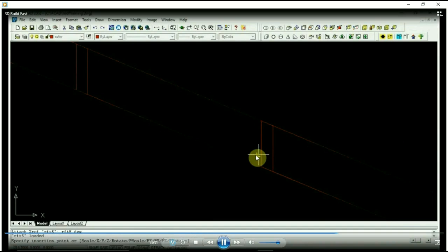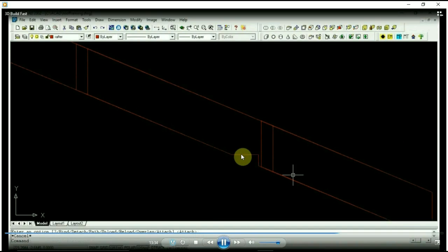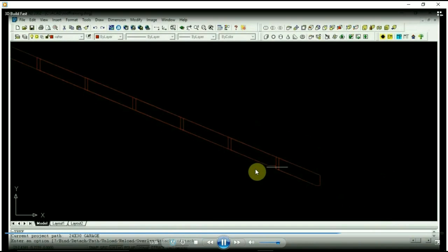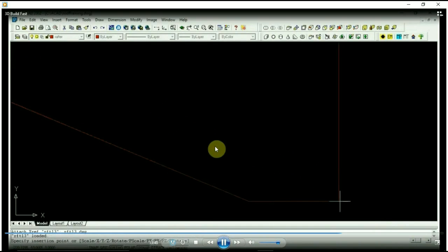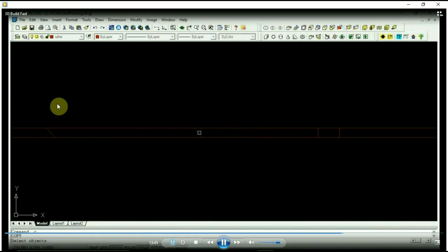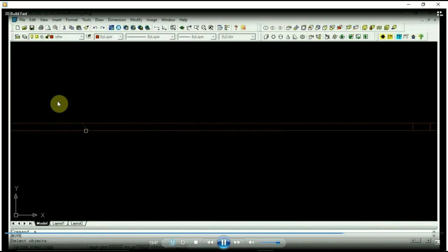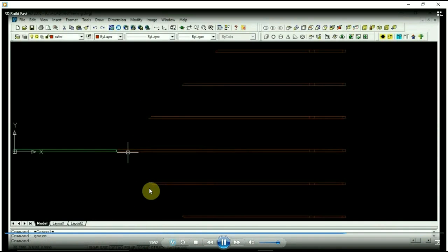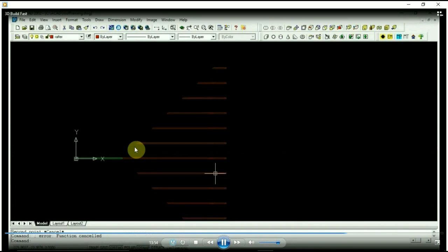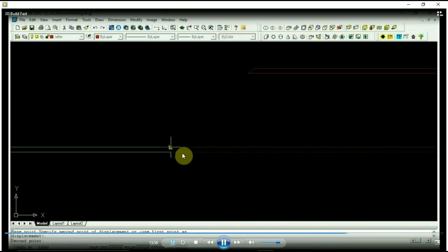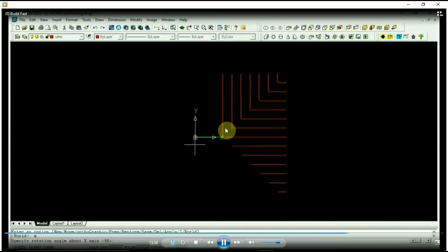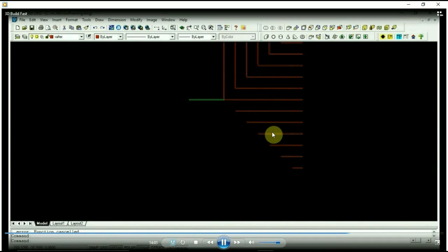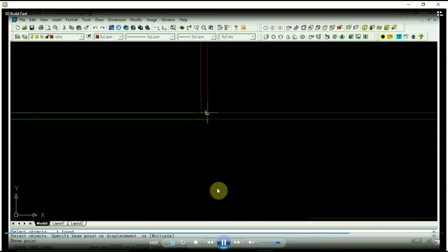And the insertion point, like I said, is right here. That horizontal line represents the top of the wall, and this vertical line represents the outside face of the wall, the outside face of the wall sheathing. That benchmark is always the same for all the roof members, regardless of their length. That's where they all work from. Now I'm just offsetting these parts the other direction so that they're on a 2-foot layout. Now I'm selecting the rafters here, and I'm going to copy rotate to make this side. Then I'm going to copy rotate this group up here to make this side down here.